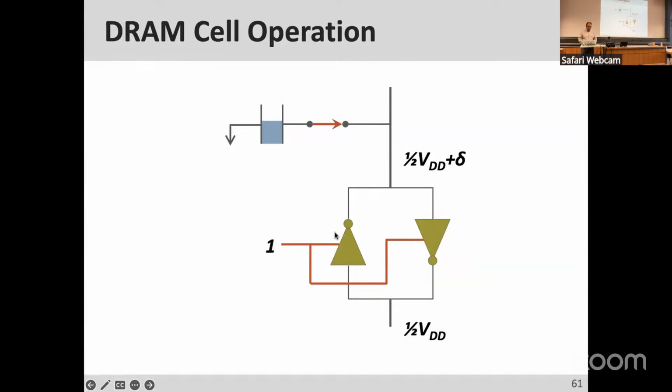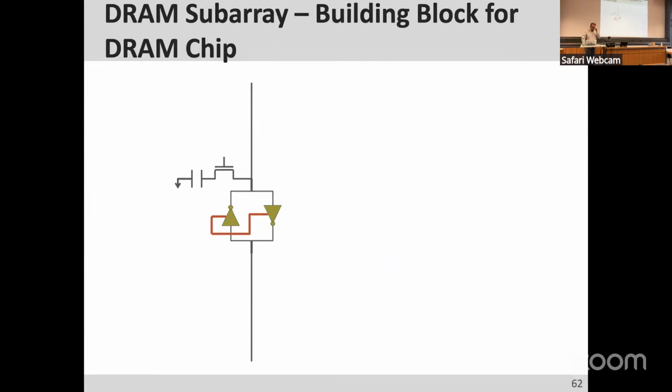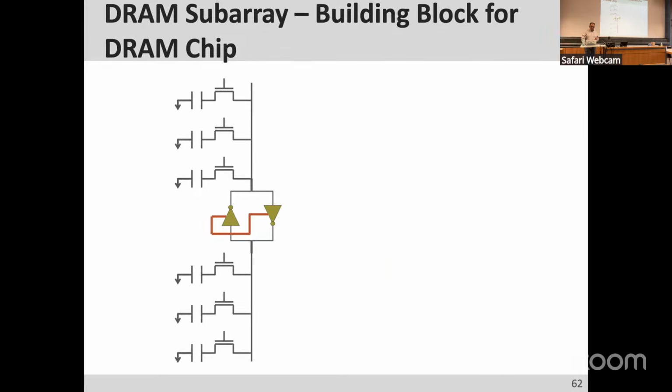After that, you enable the sense amplifier. Once you enable it, the bitline is connected to the power supply, and the sense amplifier makes it converge to the stable situation, which is VDD and 0. Make sense? Good. After that, you need to wait until you restore the charge to your capacitor, and that's the charge restoration procedure.